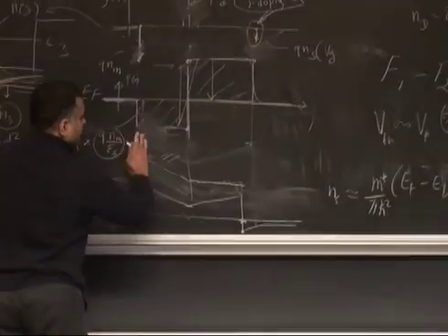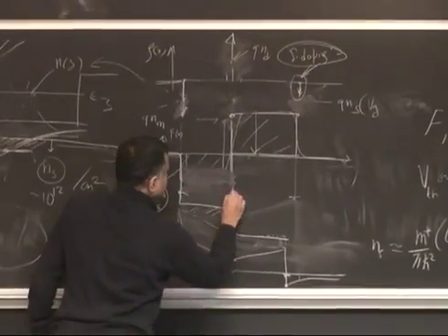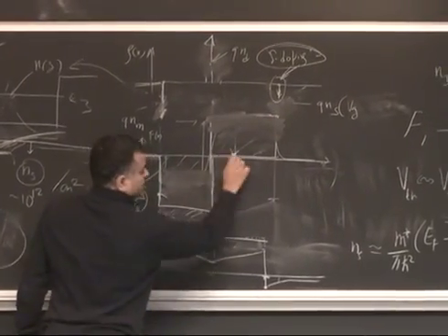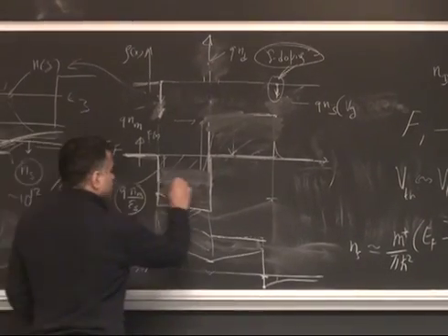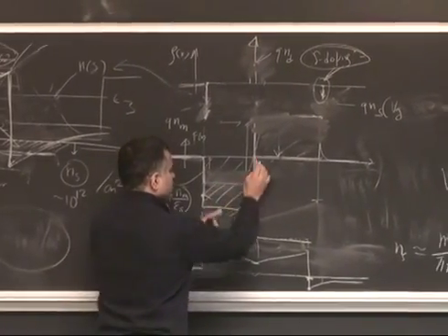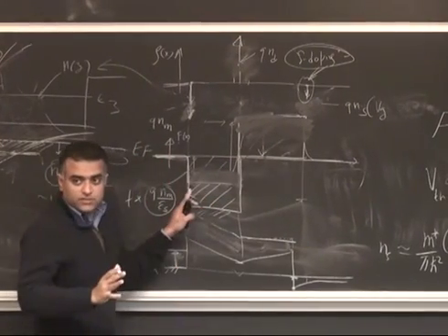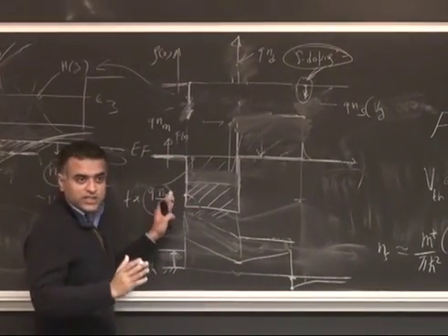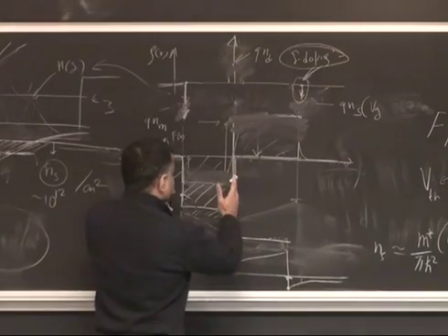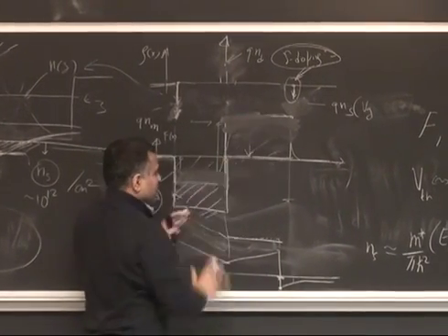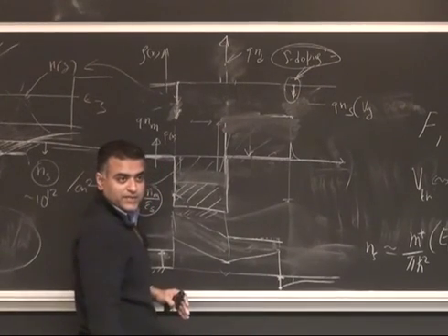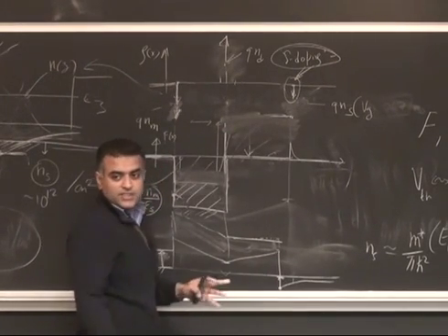And you can see why. Because once you are pinched off, all the field is here, and what's going on the right side really doesn't matter anymore. Right? So this basically, it's just the extra voltage you have applied to pull the field down to 0 here. That is it. There's nothing else left. So does it make sense? So this is essentially a pinch-off voltage, the area under the curve here, when this has been pulled down to 0, right? Is that clear?